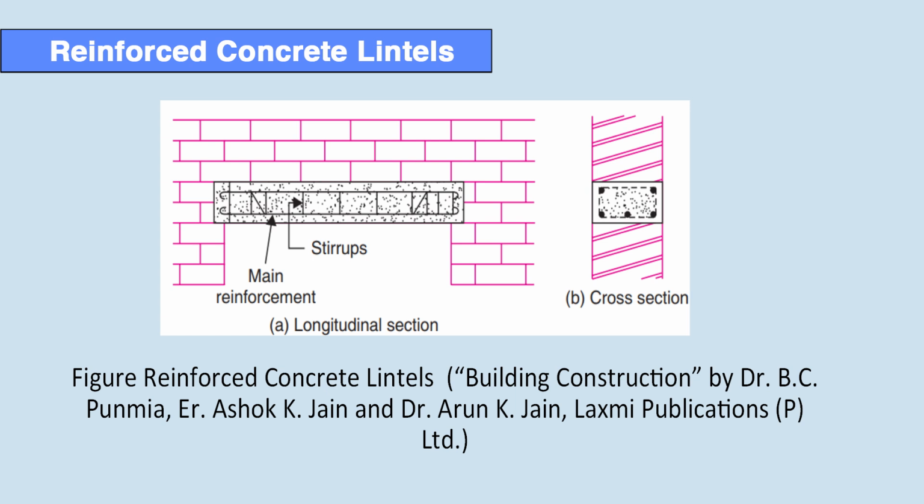When a simply supported beam is subjected to a uniformly distributed load, the bending moment diagram will be parabolic and the nature of bending will be sagging, causing tension at the bottom and compression at the top, because of which longitudinal reinforcement is provided near the bottom of the lintel. At the same time, we have to take care of the shear stresses. So some of these longitudinal bars are cranked near their ends and shear stirrups are added to resist the transverse shear.